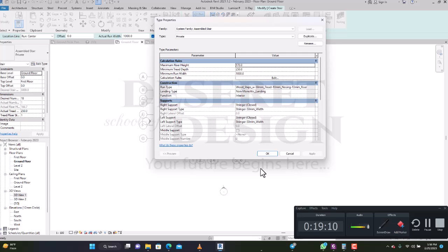If you set your maximum riser height to 150, you won't get 150, because the maximum you are setting is 150, so it can't be 150; it has to be less than 150. Everything you get will be less than 150. If you want your riser to be 150, what is the maximum that you have to set?